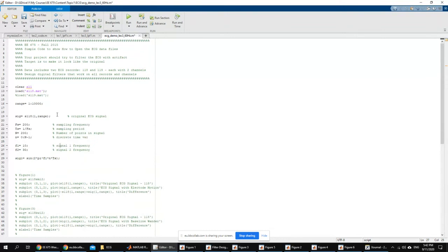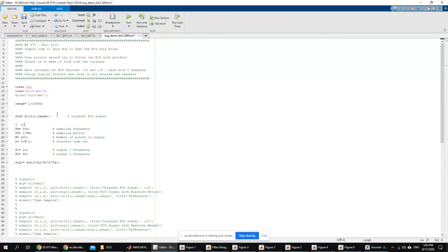And here I'm going to simulate the actual 60 hertz noise. Now the sampling frequency for the ECG signals is 360, so I have to use this exact value here. And for N, I'm going to use exactly this number here, so that we have exactly the same number.